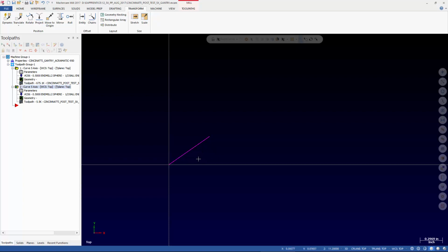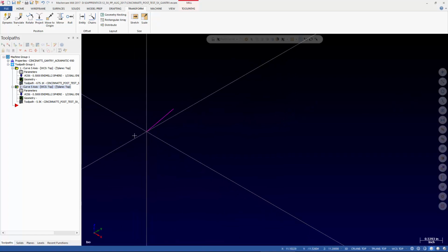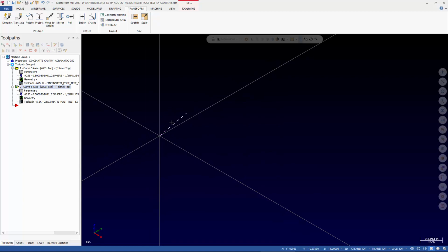So what happens? If we use a Z axis straight up and down as our primary, what we need to be able to do mathematically is rotate this vector into the plane of rotation. So our rotary for the secondary is a B. In other words, it rotates about the y-axis. We therefore need to rotate this line into a plane that's perpendicular to y. So it has to be aligned to z and x.